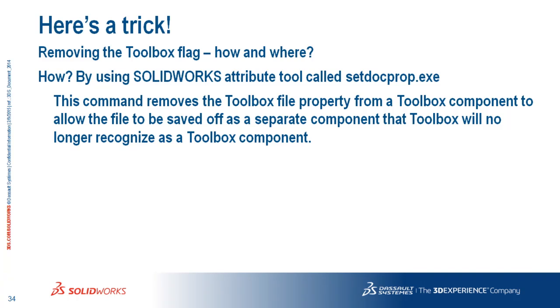So first off, what it does is remove that little flag. Now remember I said the flag that says, hey, default location here? If you want to take that flag off the parts that you make, say I save a part specifically cut to this length, give it a new name, and put it in my design library, and I don't want SOLIDWORKS to mess with it again, you have to take the flag off of it. This tool does that for you, okay?